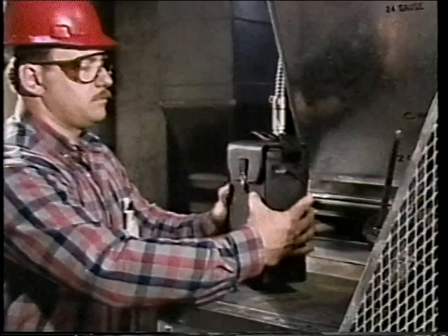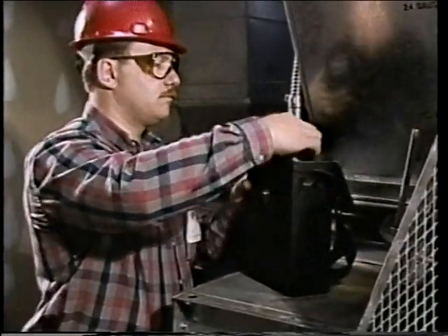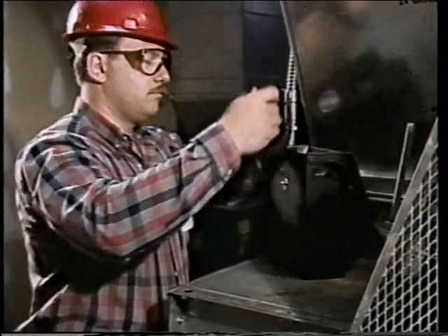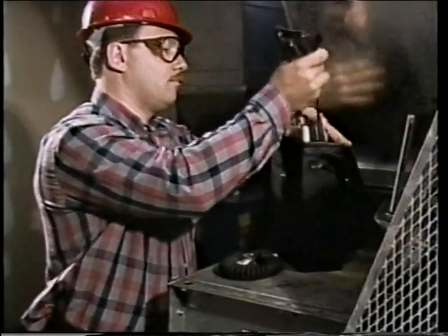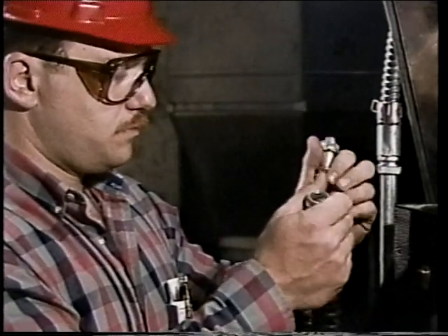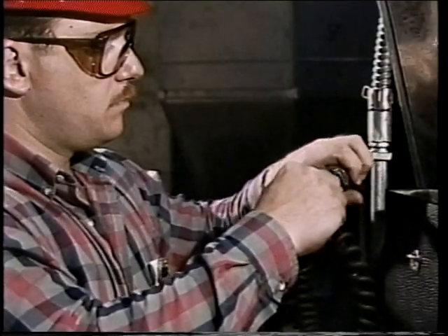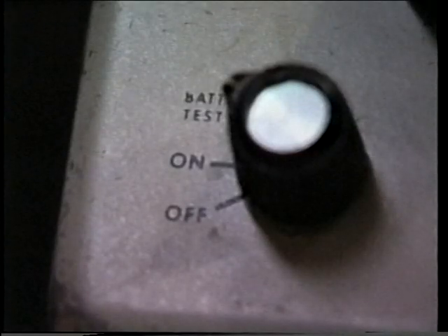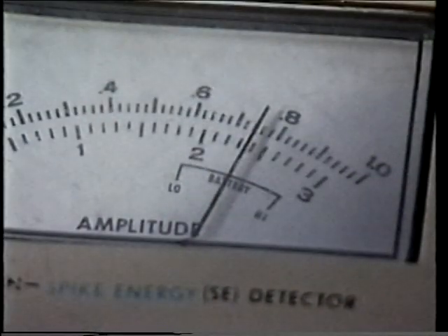When a vibration meter is used, there are a few basic steps that should be followed to ensure that the readings are accurate. One step is following both the manufacturer's specifications and your own company's procedures regarding the use of the instrument that you have. Another is checking the condition of the instrument prior to its use. The pickup, cable, and meter should be visually inspected for signs of damage. Many of these instruments are powered by batteries, which should be checked before any readings are taken. If the batteries are weak, then it's possible that the readings will not be accurate.